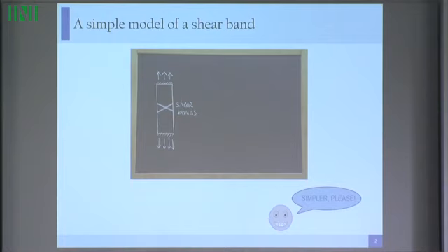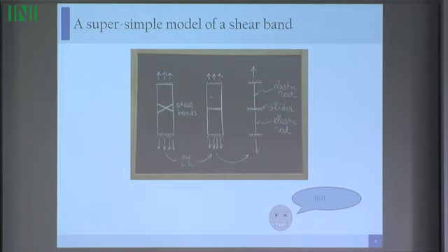So my intention was to simplify this situation, and my first thought was, why do we not put only one shear band instead of two? And then I said, we can make it easier because this material and that material will be elastic. Why not idealize both as elastic rods and the shear band as a slider? A slider is a device which allows free sliding without any friction.